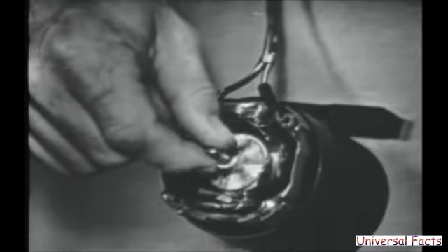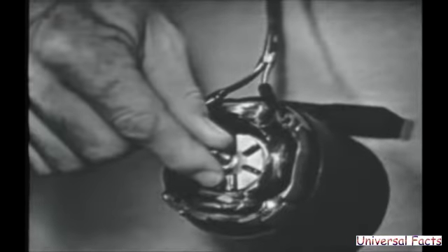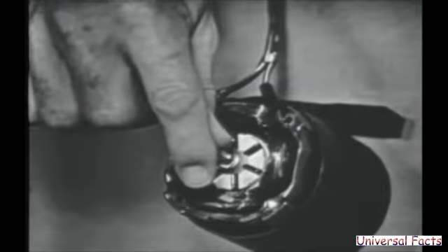Now, from this, you might think that the current in the rotor, when I've got it stopped like this, has also gone way up. But that's not so. Look at this. As the frequency of cutting, which is F in this formula, goes up, X sub L, the inductive reactance of the rotor, also goes up or increases. Now, we know if the reactance of the rotor increases, then of course the current in the rotor is going to have to decrease.